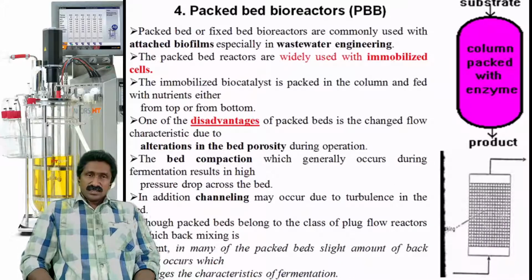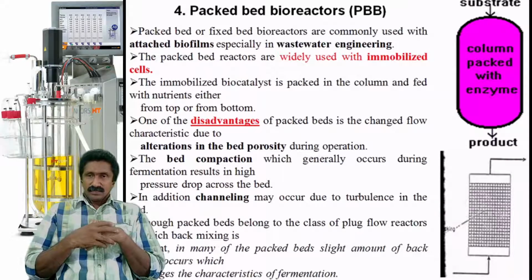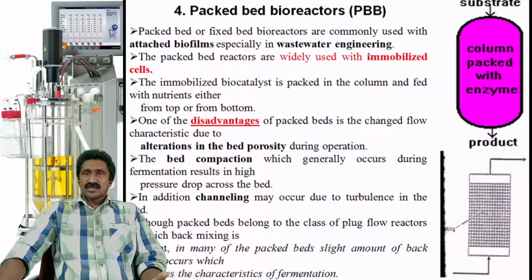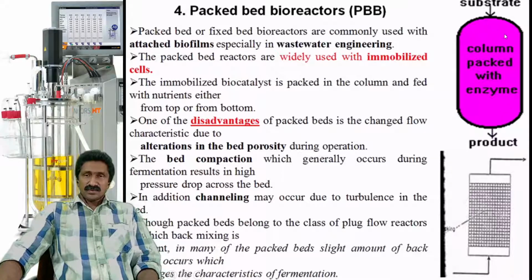Now the next one is a packed bed reactor. Packed bed reactors, or fixed bed reactors, are commonly used for attached biofilms, especially in water engineering or water treatment. There is a column packed with the enzyme. We provide the substrate and the product is taken out. Usually it is an attached biofilm or some other enzyme that is packed in the beds of the reactor.